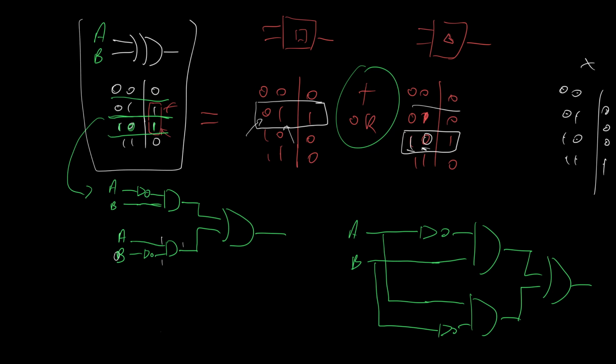So if I can write an AND gate, an OR gate, and a NOT gate using only NAND gates, then I'm done. In other words, part 2, all we are going to do is simply replace every inverter with some NAND gates to get an inverter. We're going to replace every AND gate with a bunch of NAND gates to get an AND gate. And we're going to replace every OR gate with a bunch of NAND gates to get an OR gate. And then we're done.